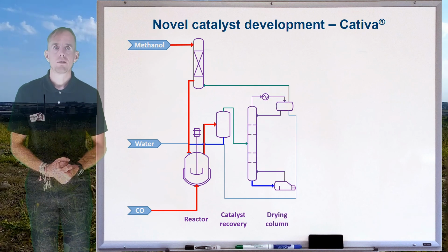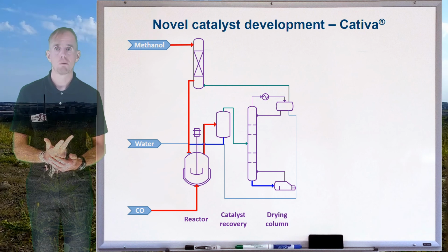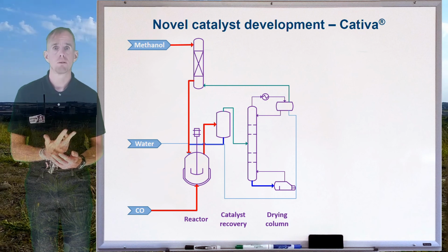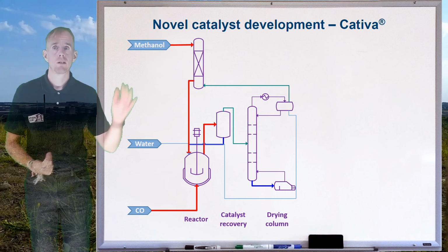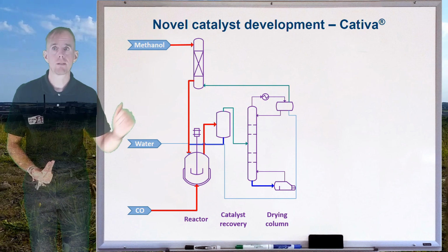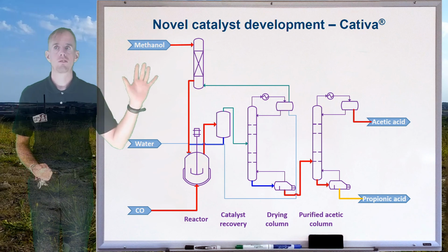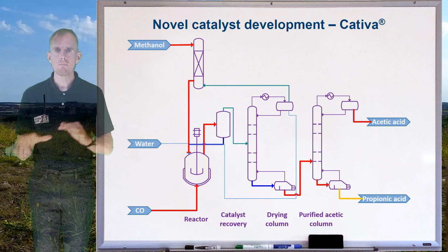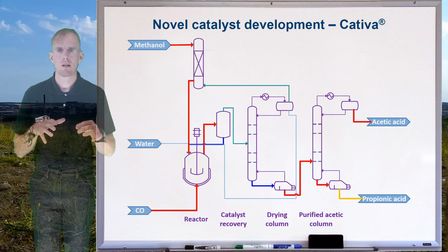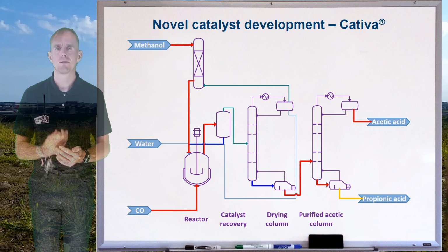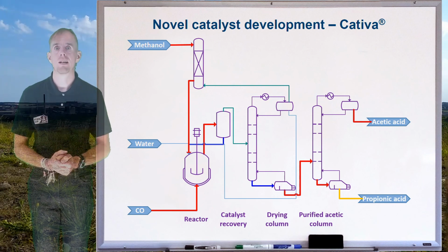After that, you've only got to deal with effectively 3 problems: water, propionic acid and acetic acid. So the first step is drying, and the second step is purification. So 2 distillation columns rather than 4, fewer reboilers, less energy overhead, a far more efficient process energetically.